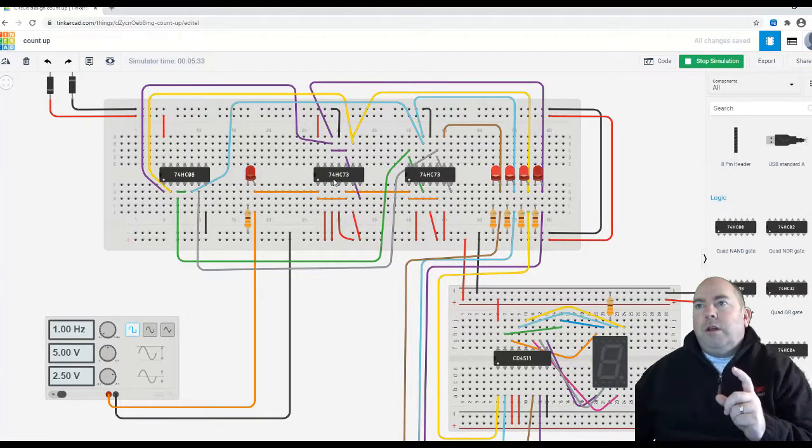of flip-flop 1 is on or not. So you'll see the output of flip-flop 1 is right here. That does a couple different things, but it also connects to K2 and J2. So if the output of flip-flop 1 is on, that will put flip-flop 2 in toggle mode. So when we clock it, flip-flop 2 will actually toggle.